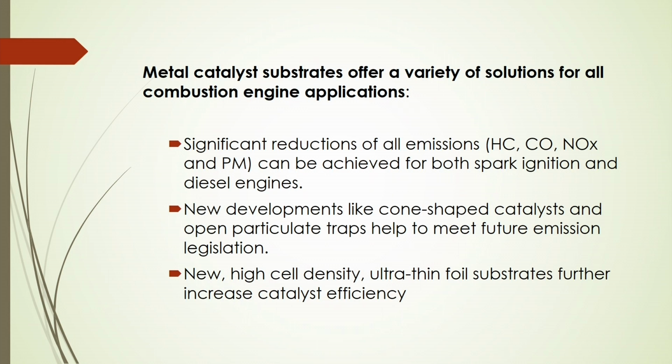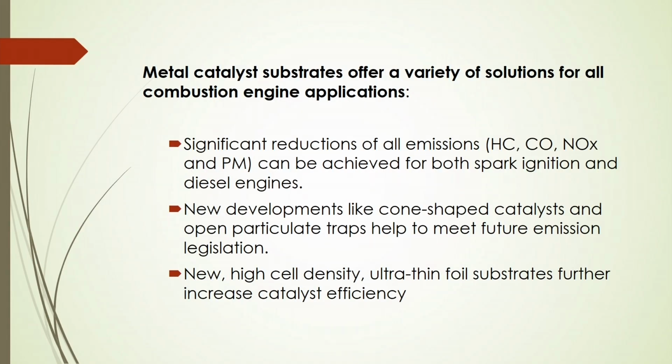Based on these metal catalyst substrates you can also develop cone shaped catalysts and open particulate traps that may help to meet future emission legislation. And new high cell density ultra thin foil substrates further increase catalyst efficiency for particular applications that you can consider. So, these are the variety of solutions for all combustion engine applications based on metal catalyst substrates.